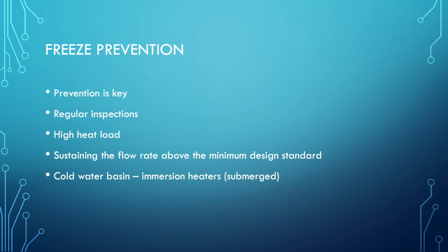First is just performing regular visual and functional inspections. Next is maintaining a high heat load. So obviously freezing is whenever the temperature gets too low. So you want the temperature to remain high, and that's maintained by keeping a high heat load.